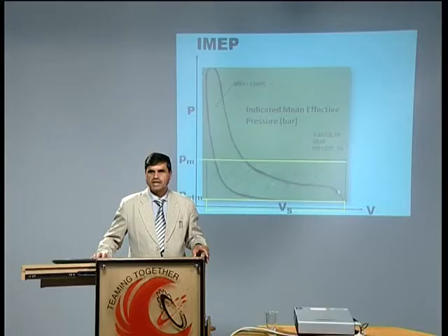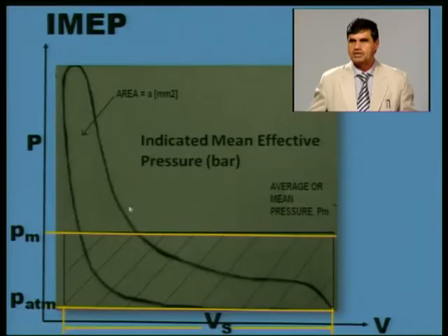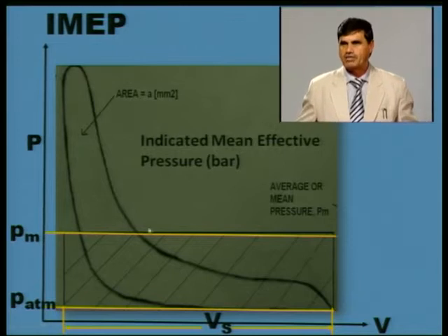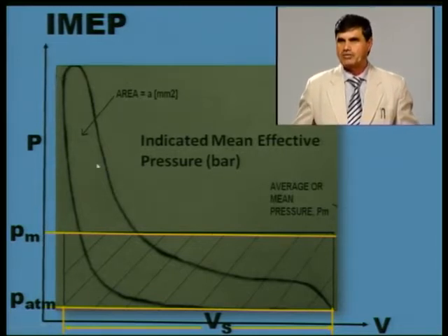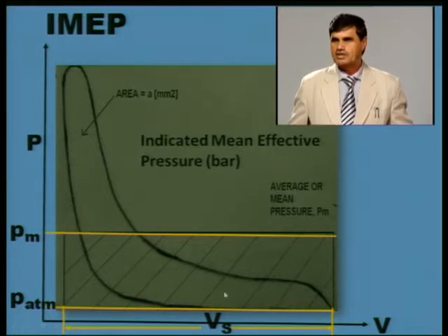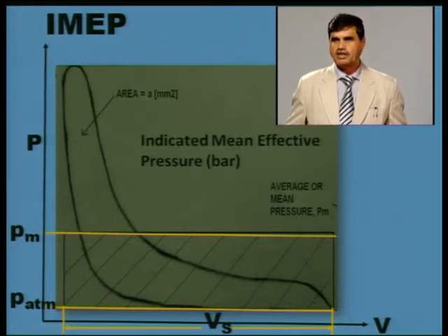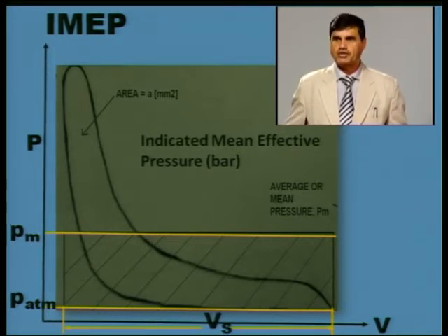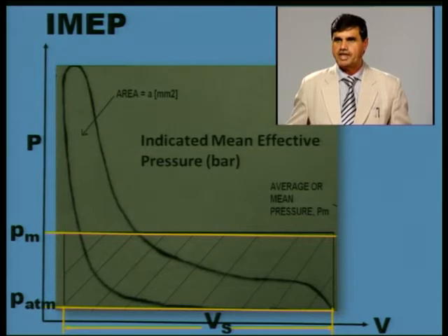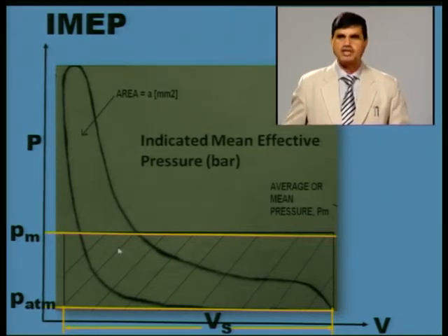This I am showing you. The upper area which I have shown you, with these yellow lines, the total area which the upper diagram has, I converted into a small rectangle, having an area equal to that of this diagram. The area of this rectangle is the output from that one particular cycle, the engine output in that one cycle, and the number of cycles per minute is the RPM of the crankshaft divided by 2. So this height Pm which is indicated is the mean effective pressure.